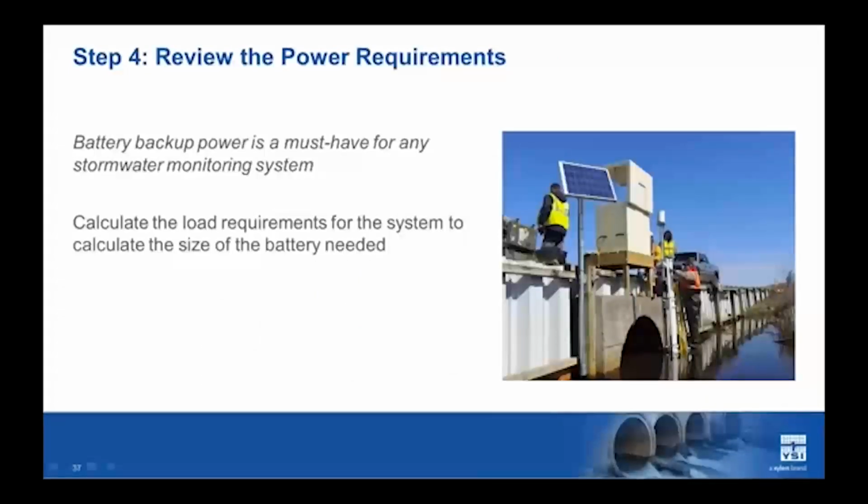All right, the fourth area, and boy, people have made this mistake a lot. So listen up. Power. When we start talking about samplers and sensors, and some of these sensors are optical sensors, the Doppler sensors always have to have hard power to them. When we start talking about that, you really need to understand the load requirements of those sensors and how much power you have to set that station up with.